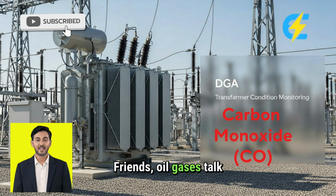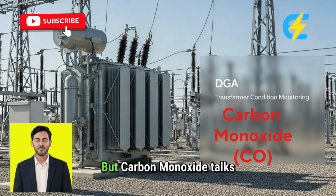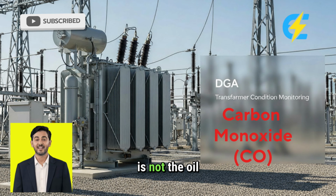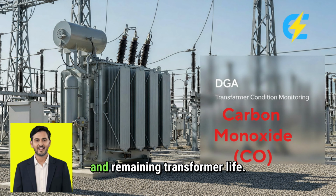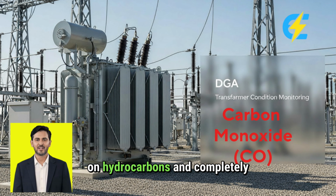Friends, oil gases talk about temperature and energy. But carbon monoxide talks about life. When CO rises in a DGA report, it is not the oil that is speaking, it is the paper insulation. And paper insulation means winding health, mechanical strength, and remaining transformer life. Many engineers focus only on hydrocarbons and completely miss this silent message.